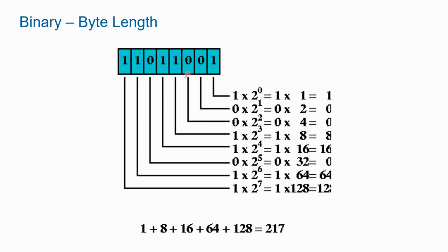Now you say, wait, this was the 4th bit, but it's 2 to the 3rd. Again, we're starting with the power of 2 to the 0, because 2 to the 1 is 2 and 2 to the 0 is 1. That's partly why we like to use 0 as a significant number when we're talking about binary in the microprocessor and PLC world. So even though this is the first bit, this would be represented as 0, 1, 2, 3, 4, 5, 6, 7, 2 to the 7th.